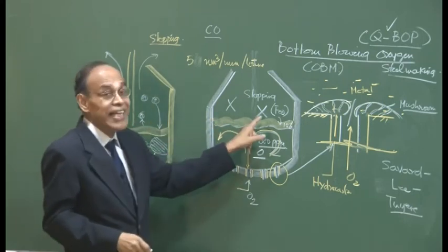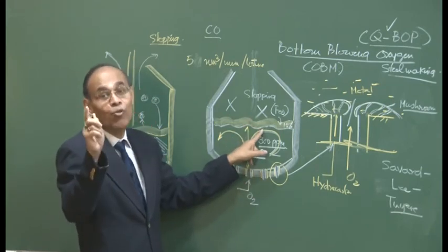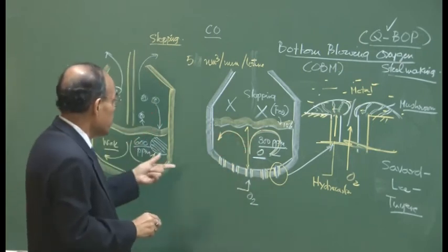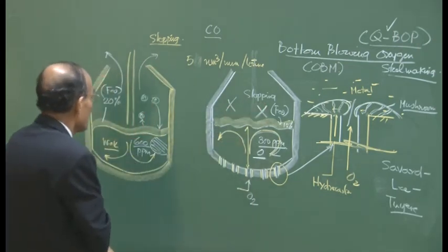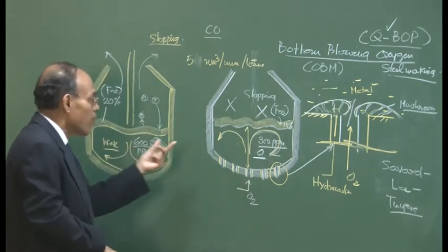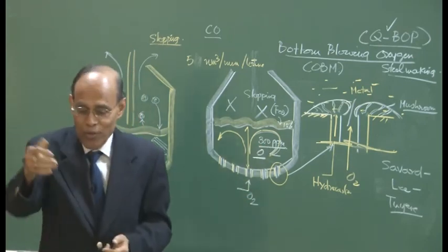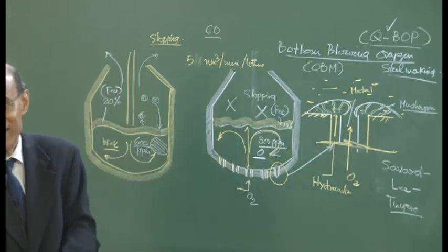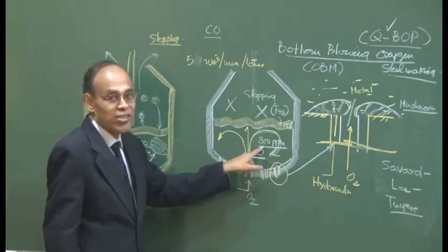So, more yield is certainly there. One advantage is more yield, and more yield means more profitability, more money, okay? We also have, as I have indicated, very rare incidents of slopping in this particular case. Iron oxide loss is rare, and we have less oxygen, which is also important, because we will see in the subsequent stage that following primary steel making we have to have what is known as deoxidation, removal of that dissolved oxygen. So, the deoxidizer requirements are also going to be small.